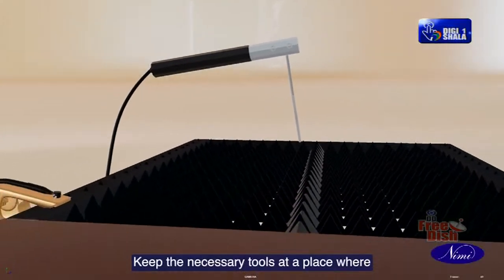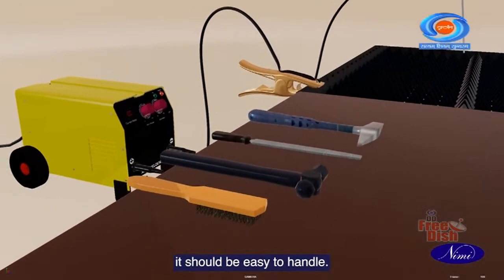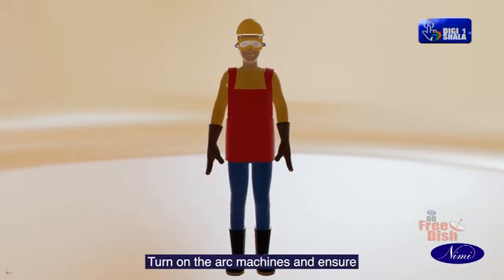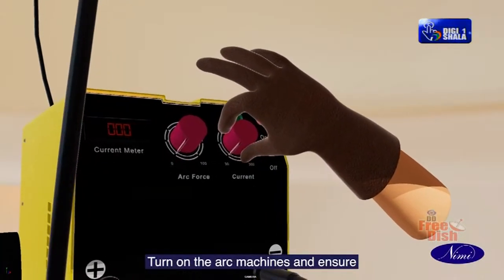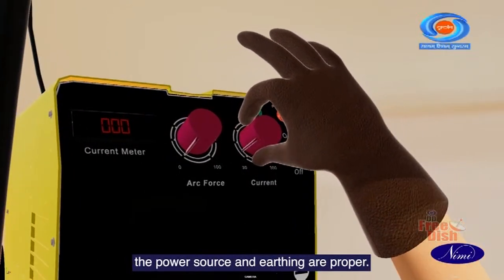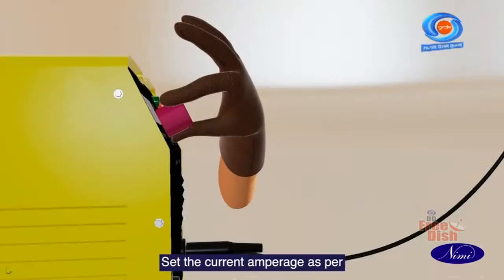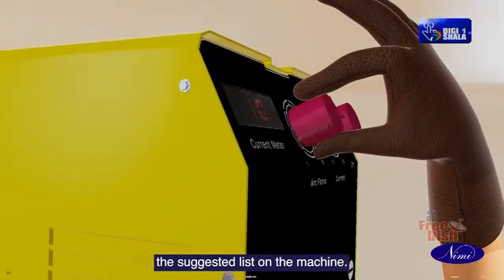Keep the necessary tools at a place where it should be easy to handle. Wear personal protective clothing. Turn on the arc machines and ensure the power source and earthing are proper. Set the current amperage as per the suggested list on the machine.